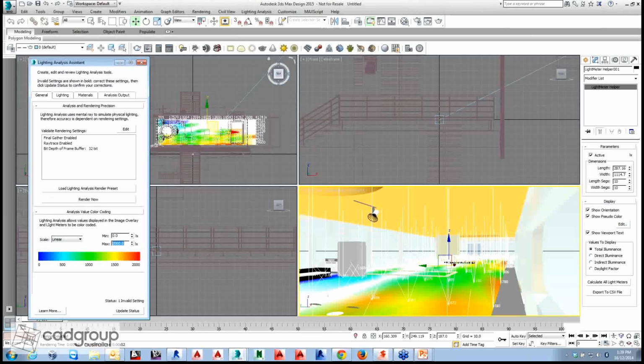So this gives me an idea that there is supposed to be more opening, or more openings have to be added in that area to get the desired amount of light. Reasonably, you always look at the charts for how much lux you require for a particular environment. For example, a living room needs 300 to 450 lux, and a warehouse needs at least 250 lux in that area.